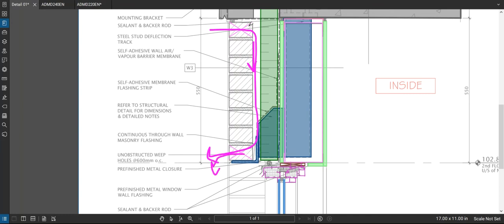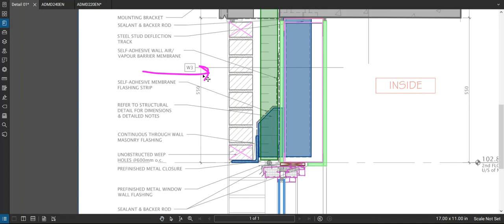It promotes drying. And the other thing it does well, if you have winds pushing on this wall and positive pressure here, having those vents and weeps will pressure equalize that cavity as well. That's kind of the whole principle of a rain screen system. So obviously it's going to take longer for that to pressurize than a more open joint rain screen cladding system, but the concepts are there.